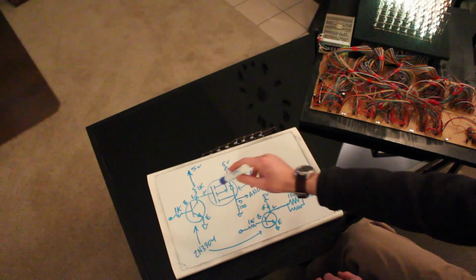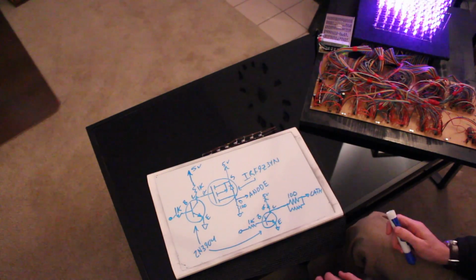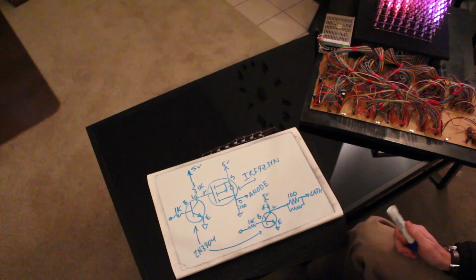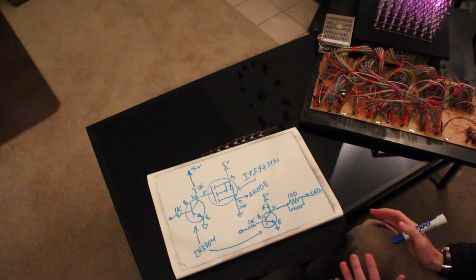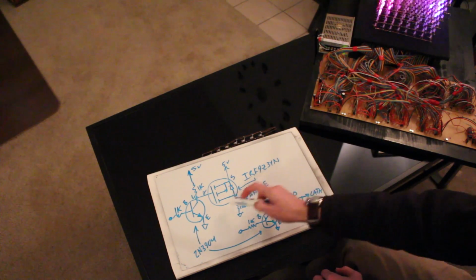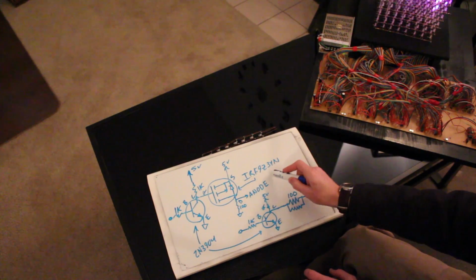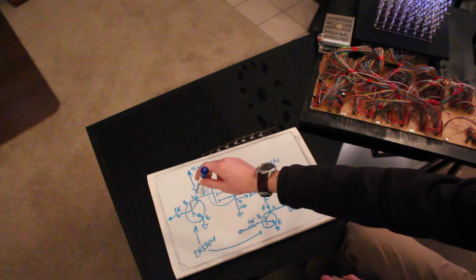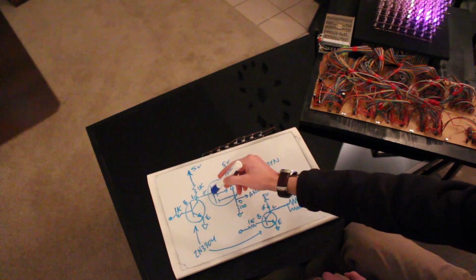And this is the driver circuit to control this thing, which is a P-channel MOSFET. I decided to use these, I guess I didn't really have to, but anyway, I decided to use them. And these are IRF9Z34N. So we have that right here, this point here connected right to the gate.